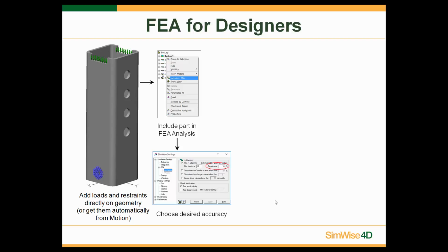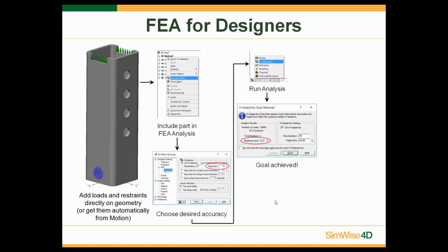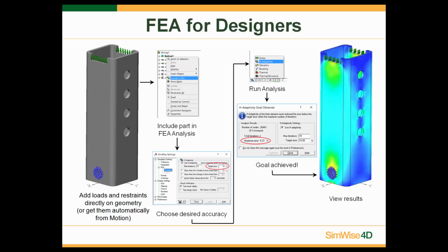of parts and assemblies. And the H-adaptive tool in here allows you to automatically refine the mesh in those high stress gradient areas. So it can be used as a hands-off approach to meshing or a hands-on. So with the hands-off, you can use the H-adaptive method, and with the hands-on, you still have access to things such as the mesh size, if you want to specify the mesh size of different parts and features, and also mesh control to specify the mesh on a fillet or a whole edge or something like that.